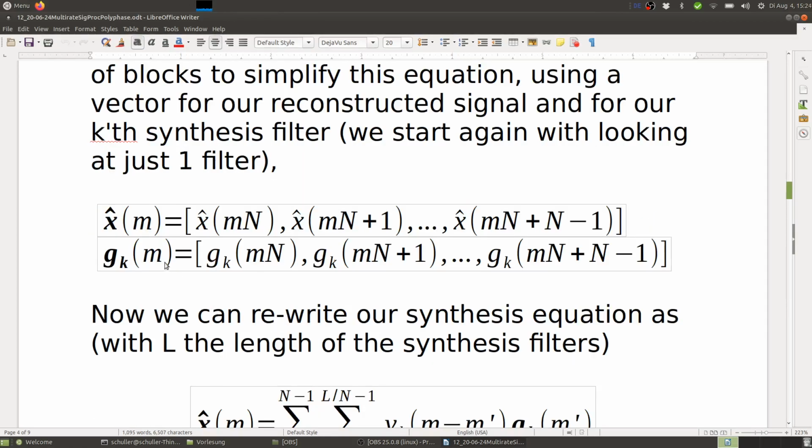And we do it similarly here for the impulse response for the synthesis filters. And observe here the phase is not flipped. Here the index goes up just like for x. Right, and this is again parallel to or similar to the case of block transforms, where we saw that the impulse response is the rows of the matrix, not flipped.